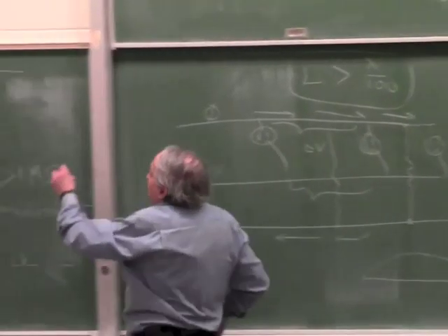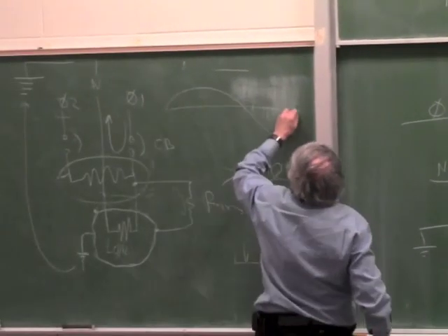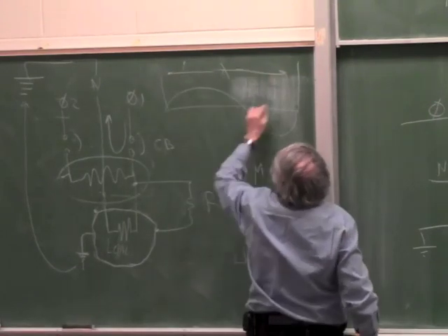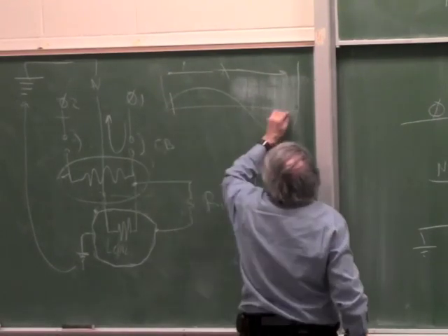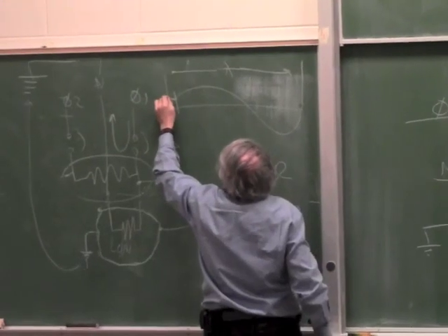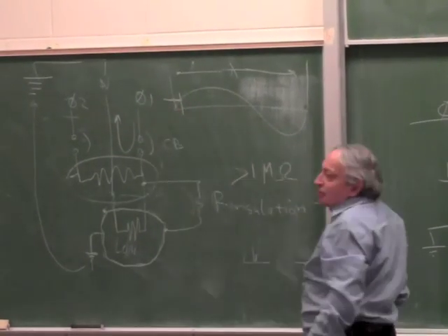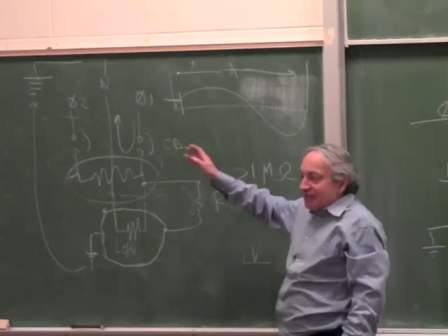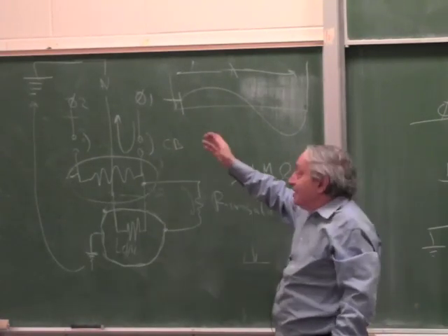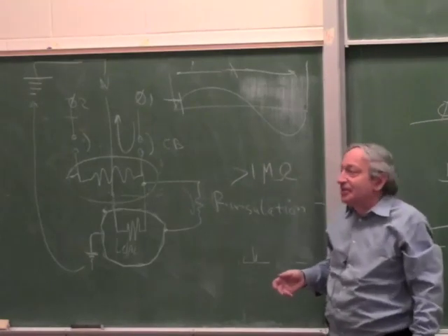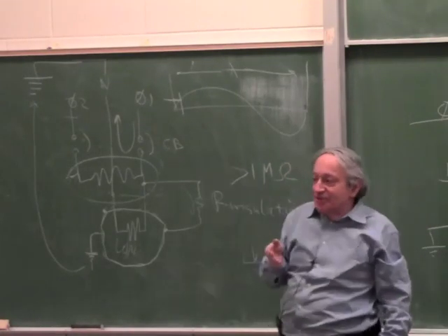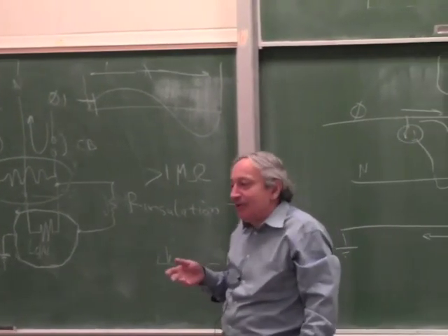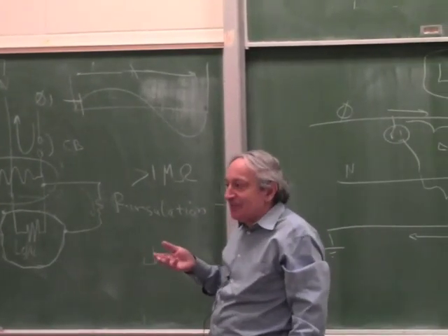Because if you have a sine wave, and this is lambda, at 1% of lambda, there is already a significant voltage, because 1% of lambda is 3.6 degrees, right? 360 degrees, 1%. 3.6 degrees, sine of 3.6 degrees is probably 0.05, it's around 5%, right?